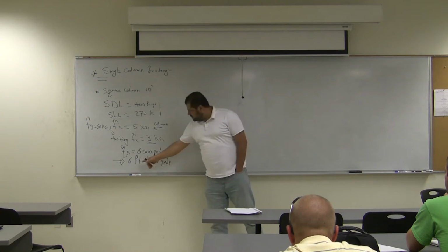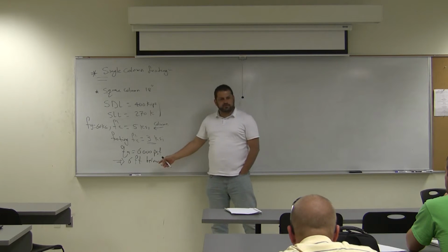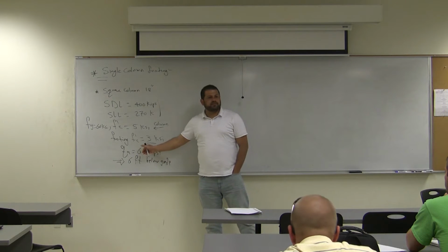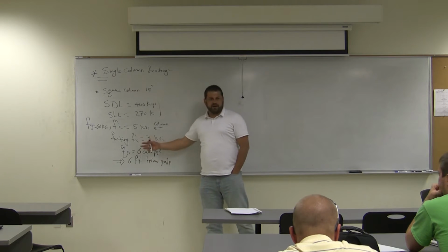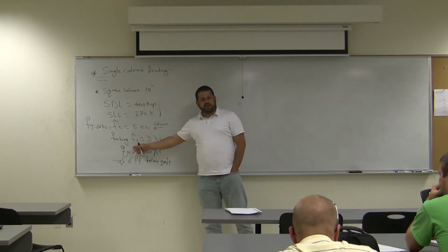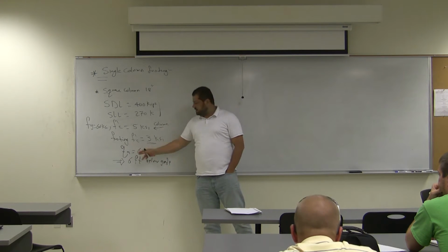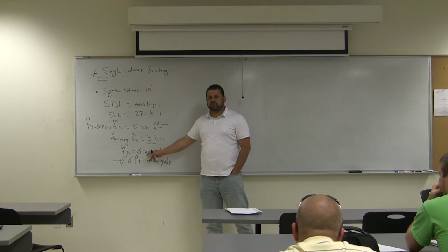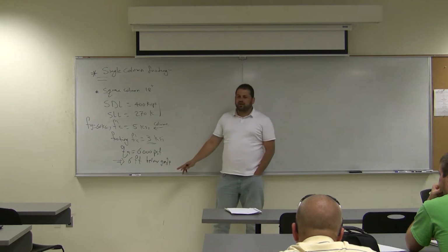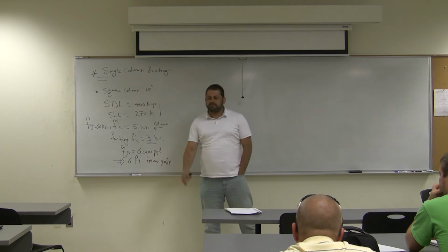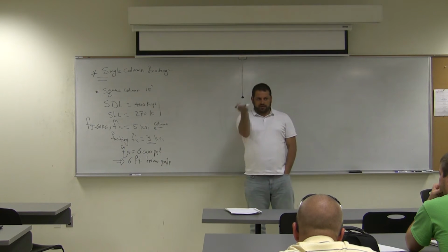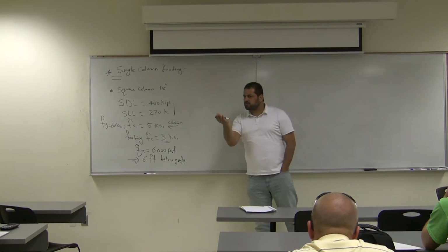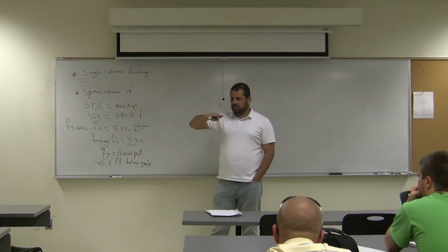So, as we said, the footing is 6 foot below grade. Usually, this is Q allowable, and that's from the soil report. They test that. The bearing capacity of the soil at 6 foot was 6,000 PSF, or 6 kip per square foot, at that level. So there is going to be the self weight of that. If it's 2 foot, 3 foot, that's going to be concrete height, and the rest will be soil.